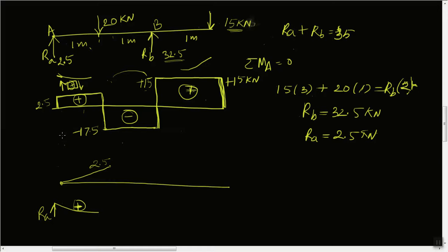Okay, and the bending moment here, if I want to find out, can be found from here at this location. Since this part is bending like this, which is hogging, it can be considered as negative. Okay, let me just erase this. Since it is bending like this, which is considered to be hogging, we have to draw the negative side of this.